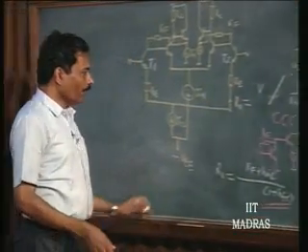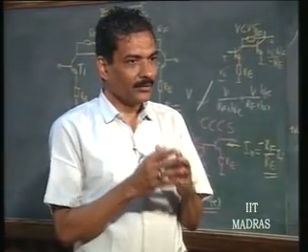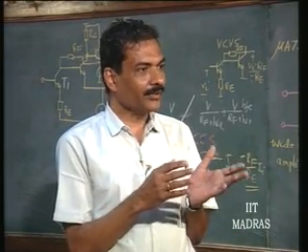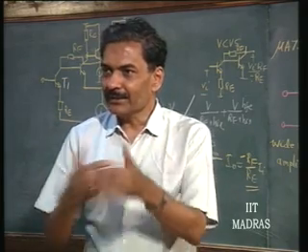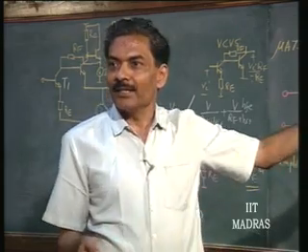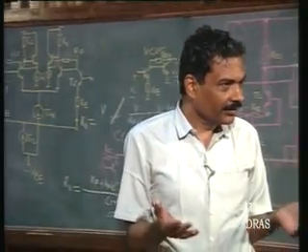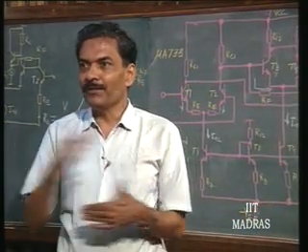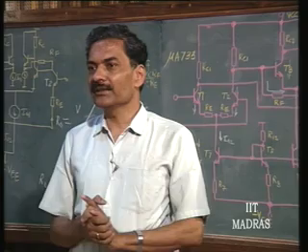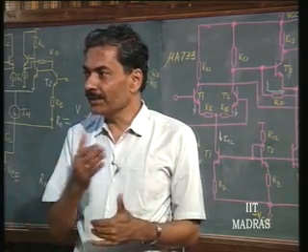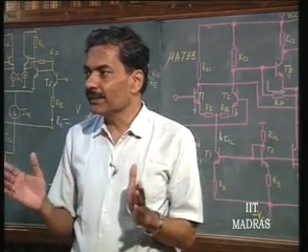So, we have now seen one such IC wherein we had cascaded a voltage controlled current source with current controlled voltage source. If you are desirous of obtaining current controlled current sources of the same gain, you have to just simply change the thing and cascade it, convert it into an IC in a similar fashion. So, now you are aware of how an IC design is conceived of, starting from a single stage structure up to the final IC, without bothering about biasing. Biasing is becoming a trivial thing, because we can use any number of current mirrors, and convert the single stage into a differential stage.